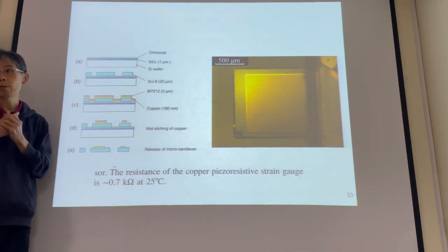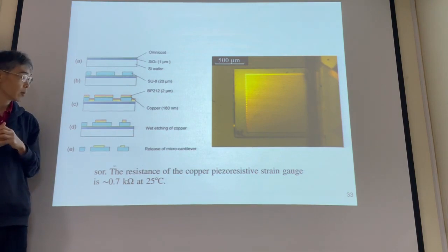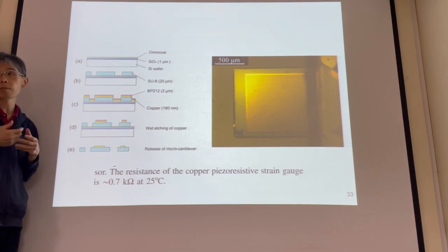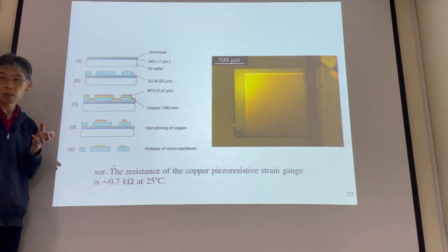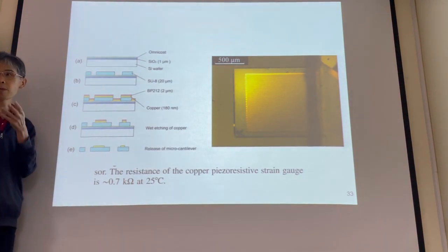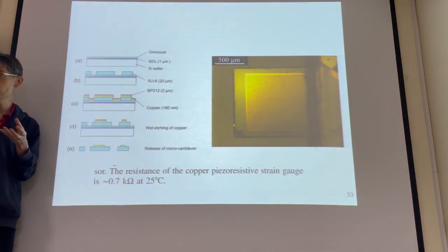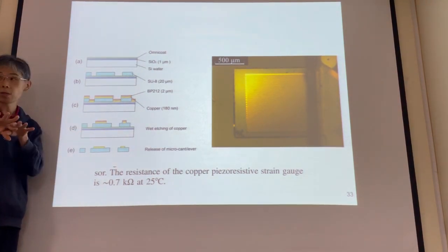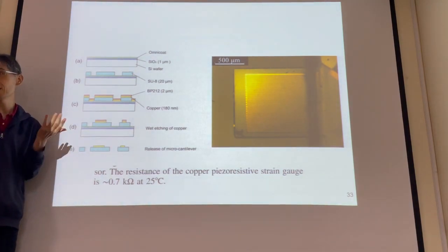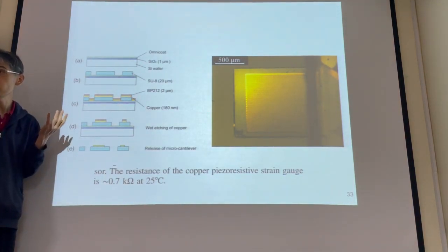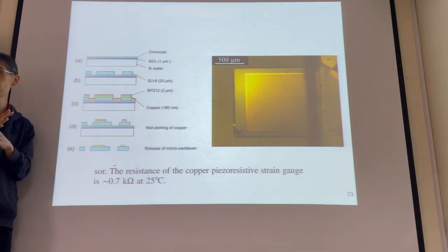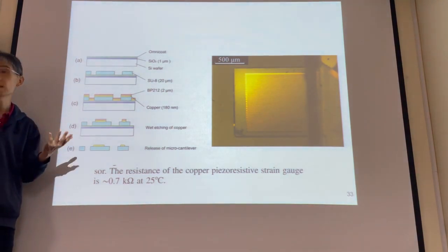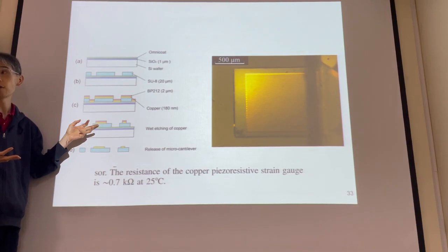Okay, that might be one reason. Another reason here: because honeycomb, we can use some agent to dissolve it. A chemical reaction. We can use a chemical agent to dissolve this honeycomb, then this one and this one can be separated. That's another reason. It's a sacrificial layer. Sacrificial means this layer could be sacrificed in order to release this cantilever beam.